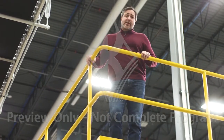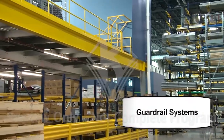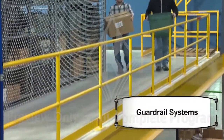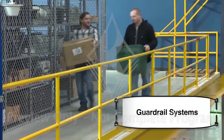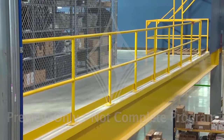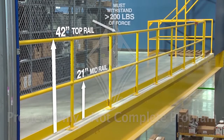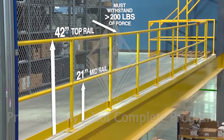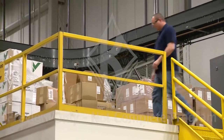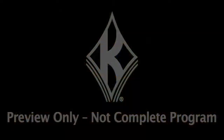The most common engineering control you'll likely find in the workplace are guardrail systems. Guardrail systems are a physical barrier used along an unprotected or exposed side, edge, or other area of a walking working surface to prevent workers from falling to a lower level. Guardrails are required to have a top rail and a mid rail. The top rail must be able to withstand 200 pounds of outward or downward force. In other words, they must be of sturdy construction and able to support a person of average weight in the event they fall against the guardrail.